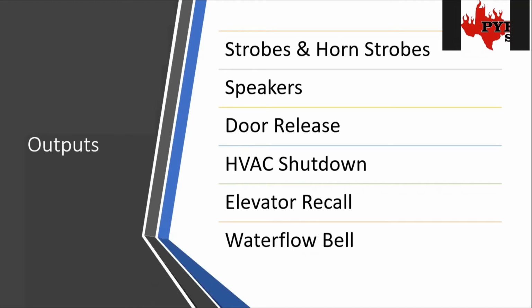Then we have door releases. I'm not going to get into access control. We've talked about possibly doing an access control and how fire alarm ties to access control doors, but also having the access side as one of these things. So I'm going to leave the access control doors for a separate discussion. For door releases, I'm more specifically focusing on the electromagnets, the door holders.